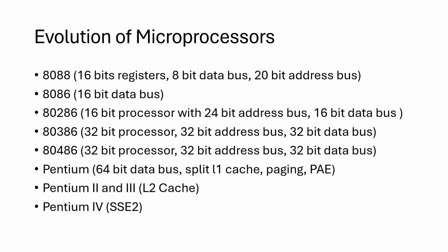After the Pentium 2 and 3, we have the Pentium 4 with some more new additional features. In this processor, we had a new cache subsystem with two levels of cache with a 128 byte cache line size, and an execution cache was provided for storing decoded instructions, and hence it was possible for the processor to remove the decoder time latency from the execution loop.